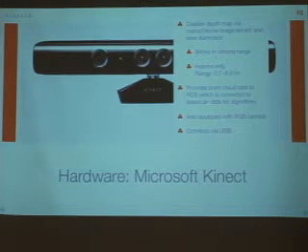The next hardware of interest is the Kinect. The Kinect was developed by Microsoft for the Xbox 360 gaming console, but now has popular use in computer vision systems. It has one IR emitter and two IR sensors, which project the depth map onto the field, which in data is point cloud data. That point cloud data is converted into 2D laser scan data in ROS, which allows us to do various algorithmic operations on it. The Kinect is also equipped with an optical RGB camera, as is standard, and it connects to the system via USB.